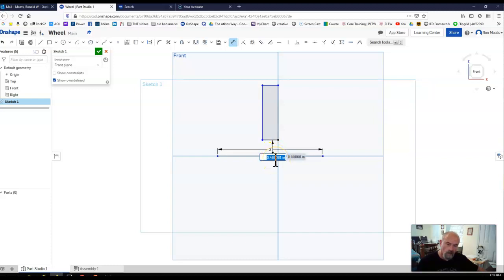I'm going to open that dialog up by clicking on that, and I'm going to set that to be 0.25 divided by 2. That will give me a 1/4 inch hole when I'm done. The center to the outside will be, if it's half of a quarter, a 1/4 inch hole.